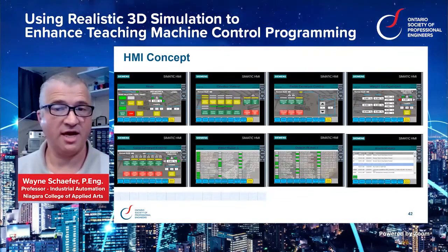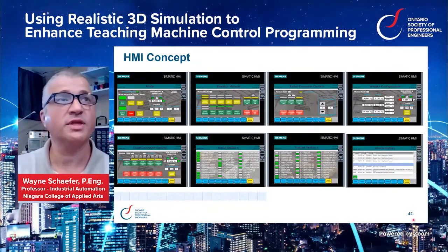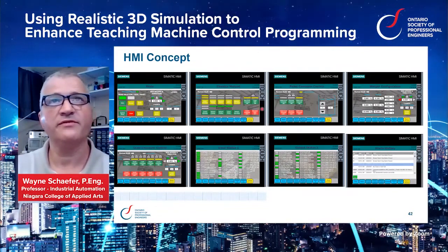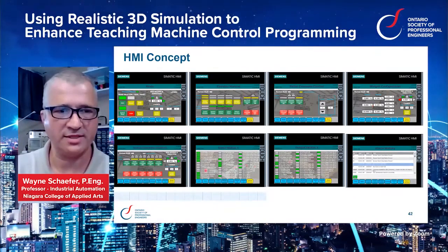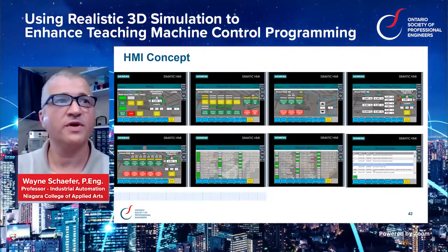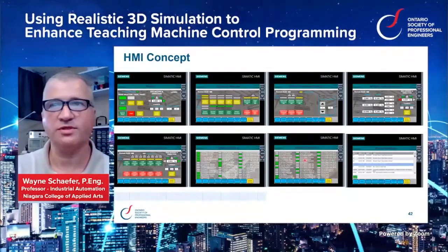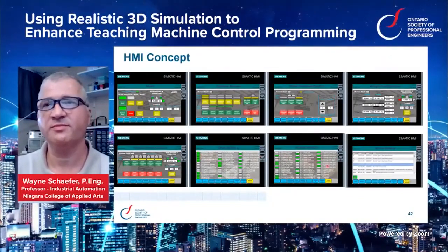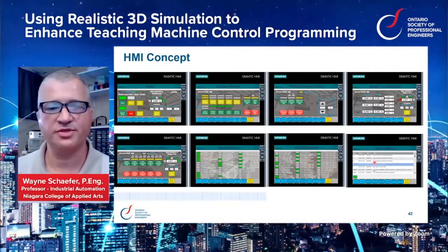So now I have a chance to talk about designing for the operator. I'm showing 8 of the 9 screens I created for the simulation. We have mode selection screen. We've got the elevator manual control screen, pallet conveyor control, weight configuration screen, which is also password protected. We've got our scale control and 2 screens for full input status and output status of all the words and IO in the system. And of course, our alarms and alarm history screen.